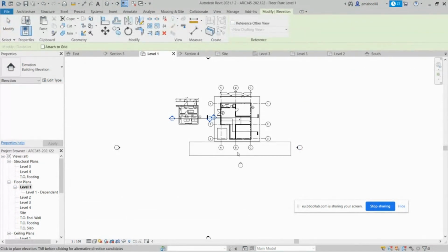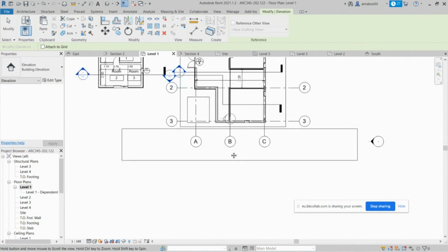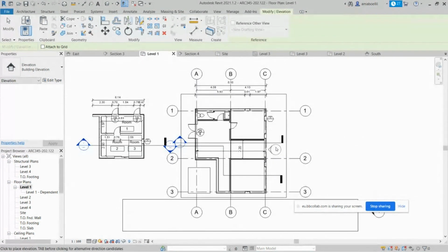But pay attention that it works like a sensor, so if you have your building like this, it will sense the elevation, so that it will change position as we go. If we track it like this and go up, if you go here, it changes 90 degrees because it senses that the elevation is in there. So this is a useful thing. And of course, if you have inclined walls like 45 degrees or 30 degrees, it will sense it and then readjust according to the 90 degrees from that wall, so that you don't have to struggle with any projection.